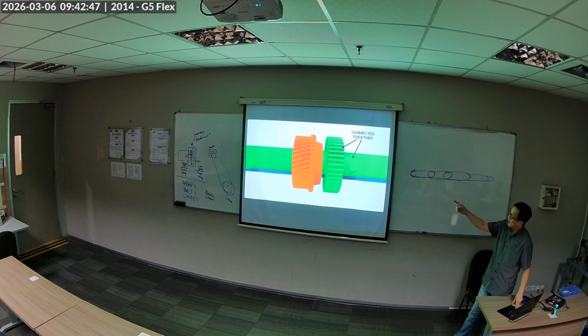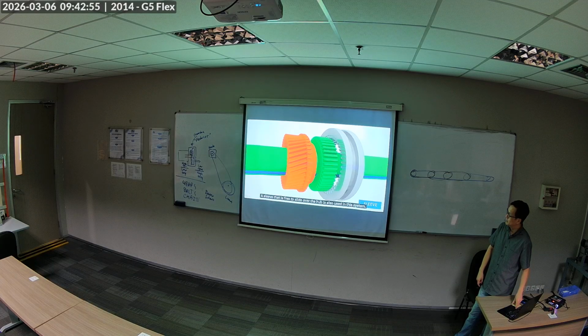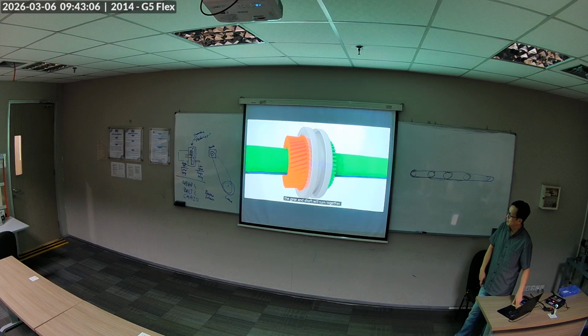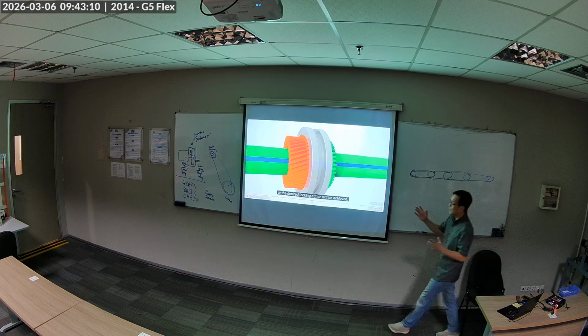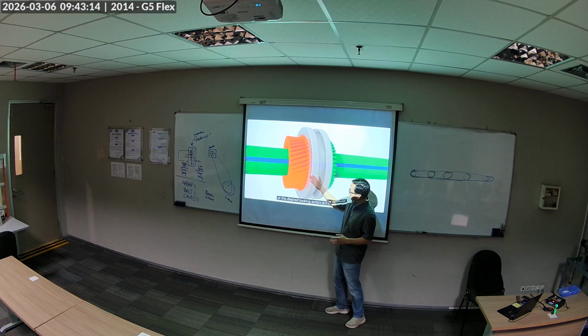And the red one floats. A sleeve that is free to slide over the hub is also used in this system. It is clear that if the sleeve gets connected with the teeth of the synchronizer cone, the gear and shaft will turn together. Okay? So this is how you lock them together. This gray part will slide and connect them together.